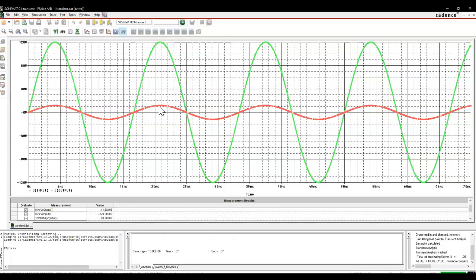And then from this 12 volts, I might convert it to a 5 volt signal. It's still AC, and as I said, we're going to want to convert it to 5 volt DC, which is what we're going to work on this week and next week in your simulations and homework. So you can kind of see, and again, you don't need to know all the circuit theory details. We have the basic circuit theory of what a capacitor does and what the diodes do, to have an idea of what's going on in the circuit. We don't have to understand all the precise equations.